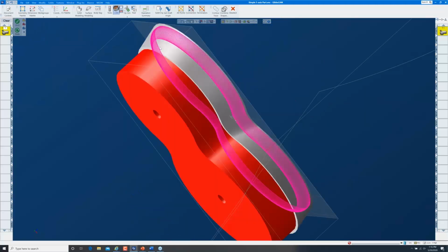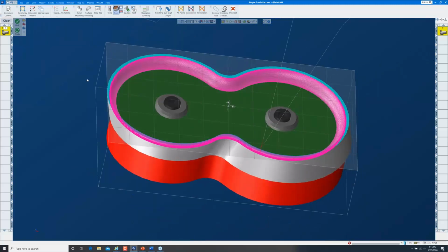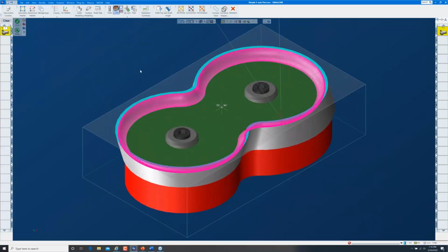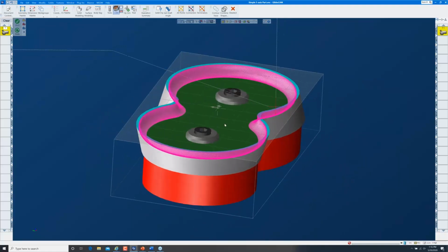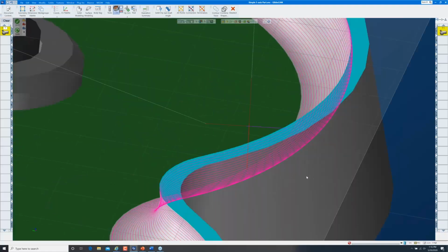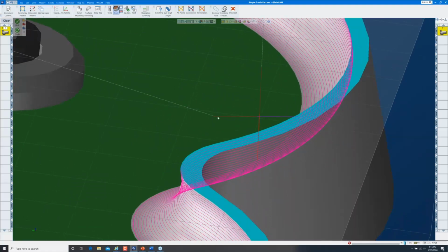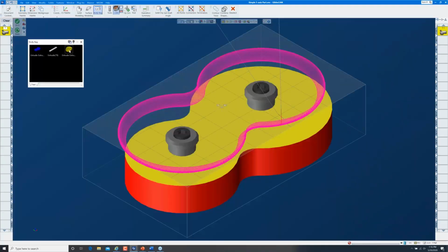What we fail to do is to adequately control the axis of the tool or the center line of the tool. Some people think of it as controlling the back end of the tool. And once you have some time in this environment, you would have realized right away just by looking at this entry move and this exit move that the tilt of that tool was not quite what we had in mind.